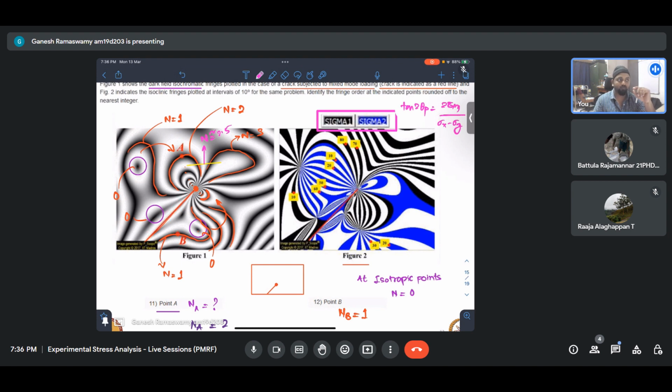These are essentially called ambiguities. And these lead to, when you use phase shifting techniques to discern the isochromatic data, something called inconsistency. There will be a sudden jump. For example, if you have one point where the isoclinic angle is reducing, 10, 5, 4, when you go to 0, you expect there will be a pi jump. Suddenly it will start from 90, 91, 92, like that. So that jump comes because tan inverse of x is a multi-valued function.